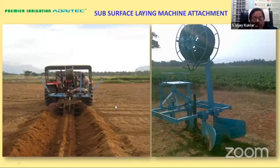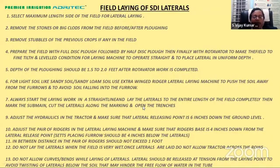So this is the tractor attachment that is there, and the drip coil will be put on the coiler, then it passes through the tube over here, and then directly at the required depth, the attachment will ensure that the drip lateral is laid at the required depth. So this is the thing. Field preparation and land preparation, all this has to be done. It has to be a level field, and then you can go about doing the entire laying of the subsurface drip irrigation laterals. And here I would just like to elaborate in a simple way what all the steps are.